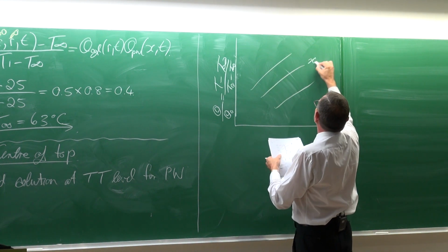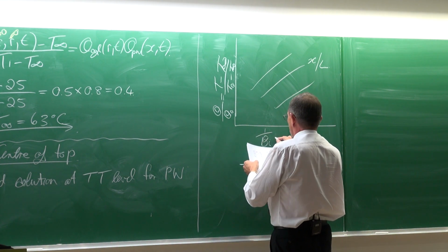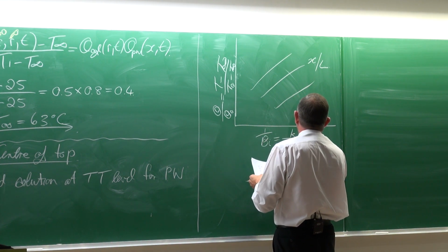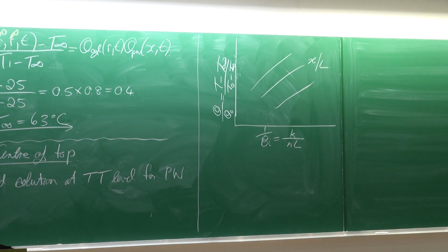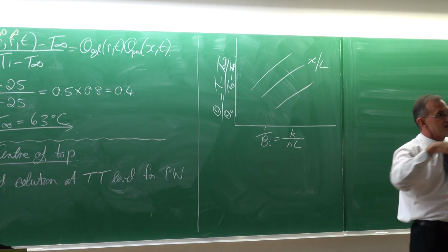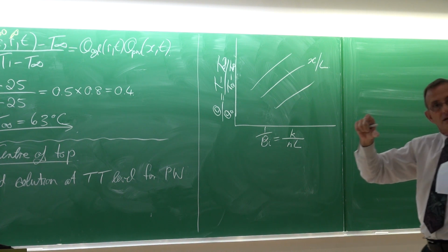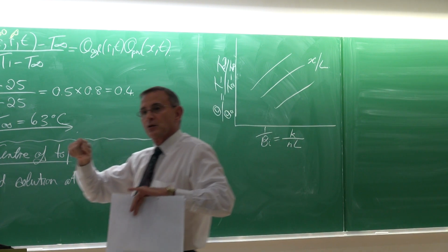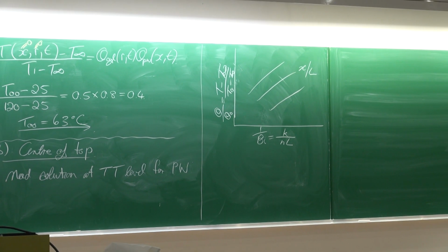This is as a function of x over L, and 1 divided by the Biot number is equal to k over hL. In the solutions, the sum from n equal to 1 to infinity, there is a place where you do the cos of x divided by L. You're just going to put it in there in terms of the calculation. Okay.